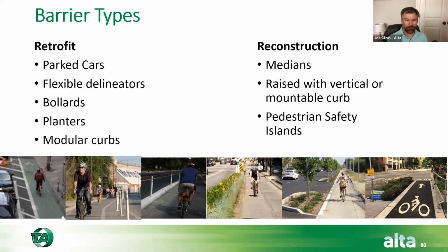Now, there's still a lot of local agencies and states that still have clear recovery zone requirements that contradict what FHWA is saying, that you don't have to have them. Clearly, if you don't have things to hit, you're not going to hit them as a vehicle. And so that's one thing to be considering.